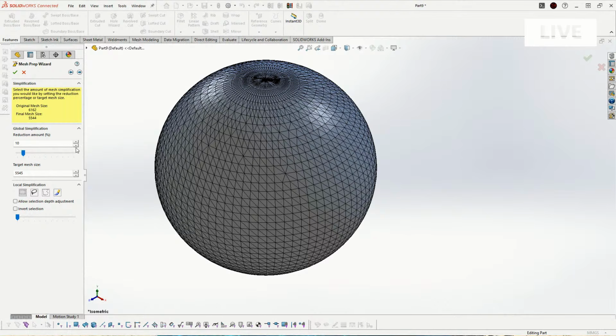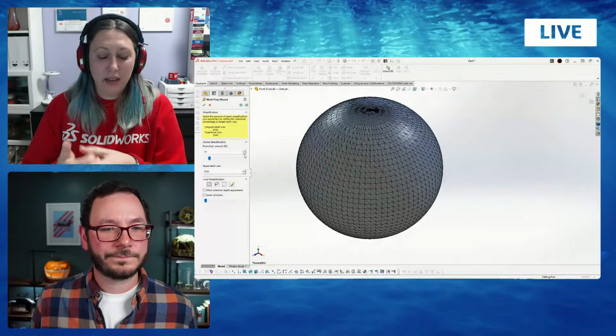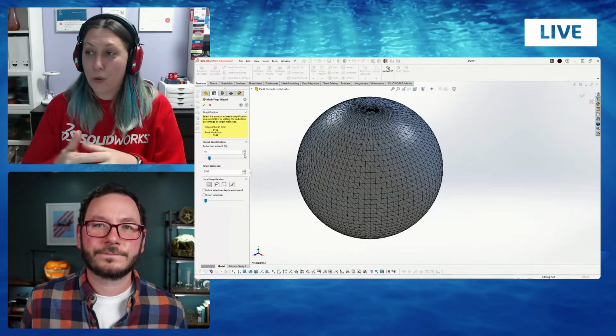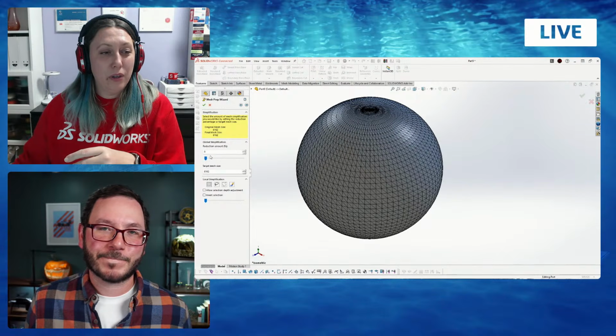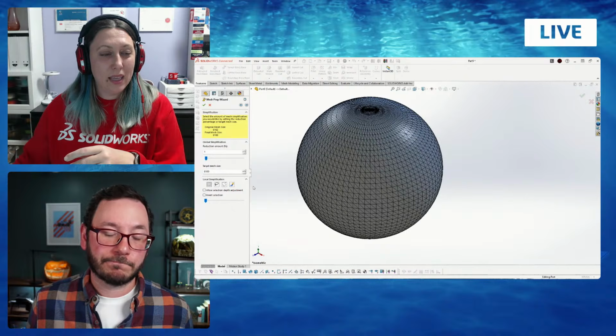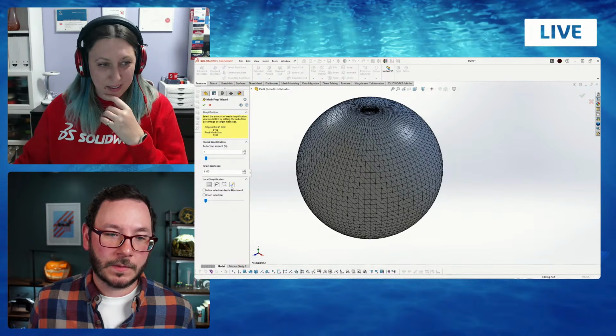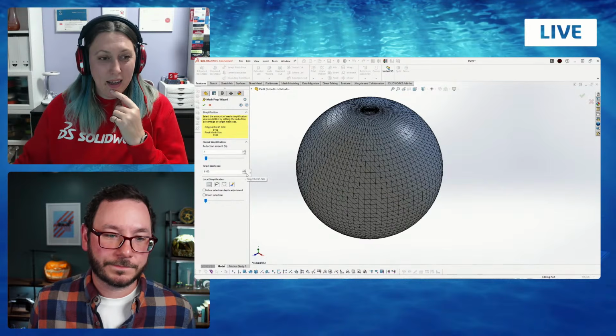A very interesting trick actually, if you have a mesh that has errors, but I will show this one also, it's better to reduce the mesh at least by 1%.